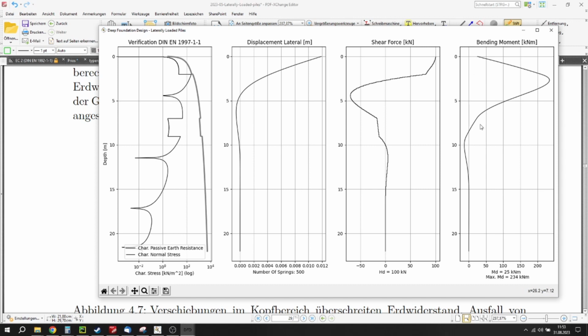Not only are the internal forces too high, but also the stress that is going to be generated, even if the pile could bear these internal reactions. It will just push the soil away, because our soil is not good enough in the top layers.